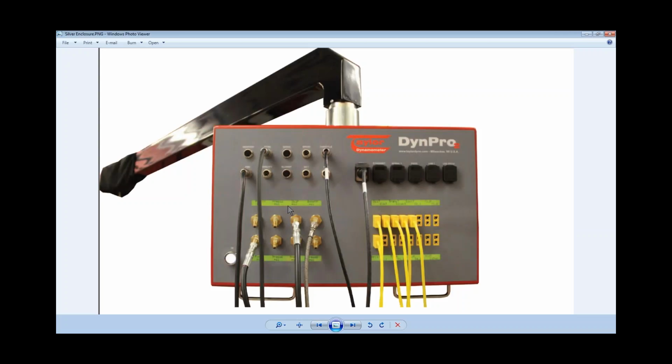What happens when you select that button, we can change from the actual value being measured to the actual name of the channel. On the pressures, we'll have the name always listed, and then we'll differentiate between the actual units, so PSI or KPA, whatever's listed, and when you select the button, it'll change over to the actual value being measured. And on thermocouples, we go from the name to the actual value in degrees C or degrees F, whatever the system is set up to view.